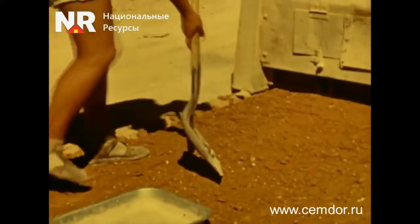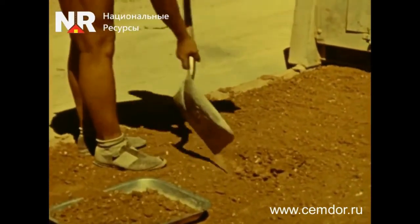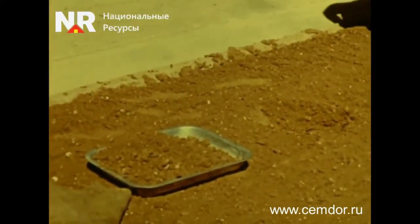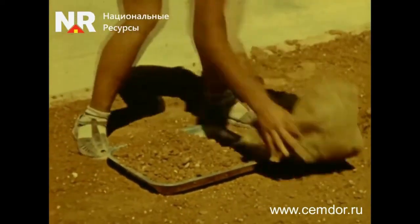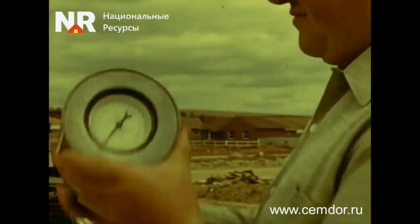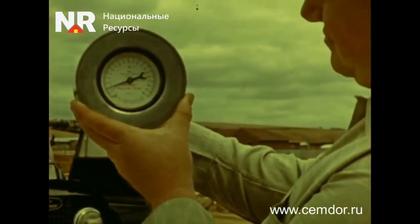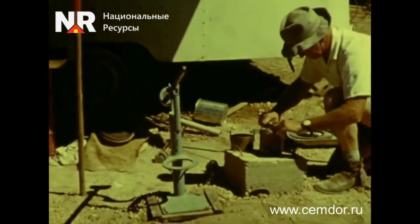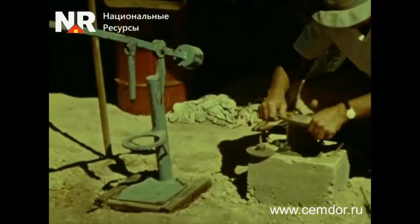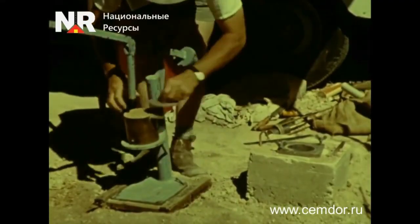Sampling of the mixture is carried out immediately after the passage of the mixing machine. They are used to determine the optimal amount of water in the mixture to ensure maximum density. Its quantity is determined using special equipment. The design strength of the soil cement is determined by studying the strength characteristics of soil samples molded from the laid mixture at the site and tested at the design age.